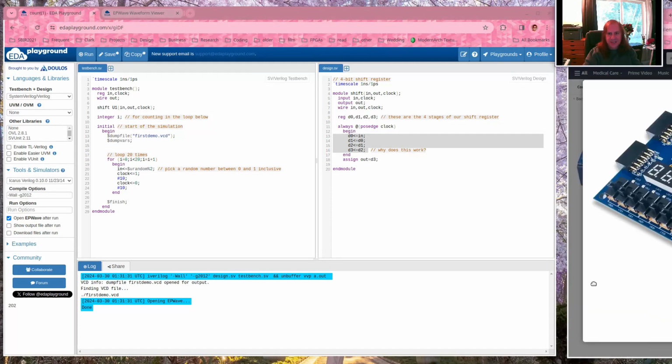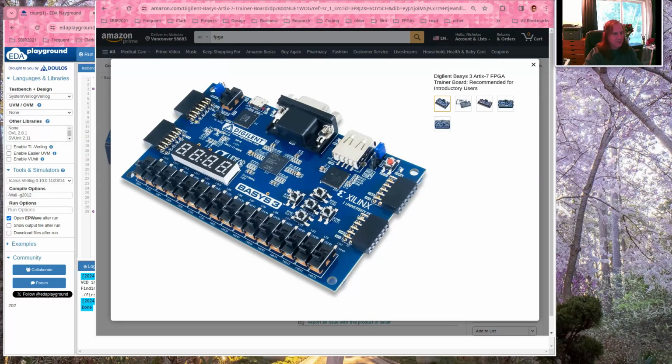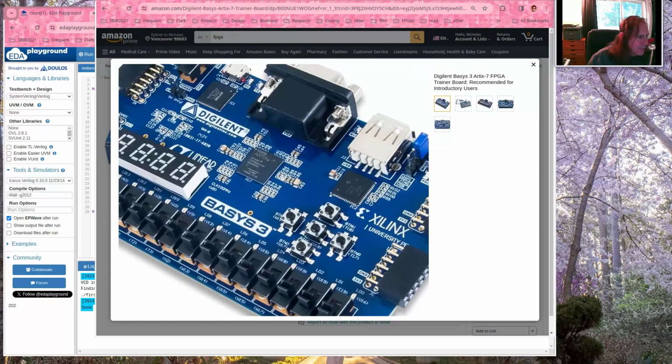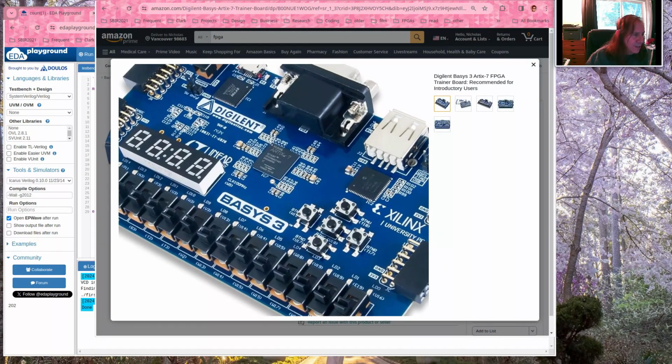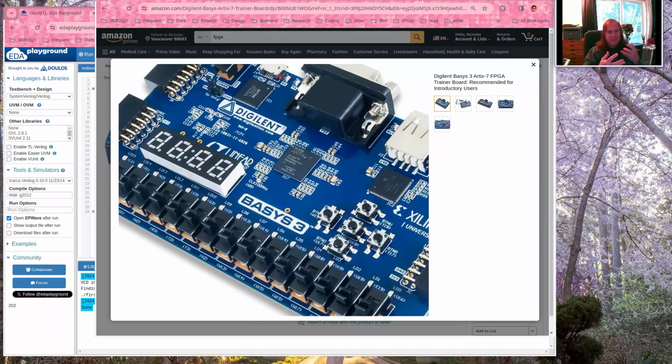And FPGAs, you can get them on development boards like this, and basically it's a small chip like this one right here, made by a company called Xilinx in this case, and it's got a whole bunch of logic inside. It's got multiplexers and demultiplexers and input and output ports and so on, and by loading values into memory inside this chip, we can connect components together.